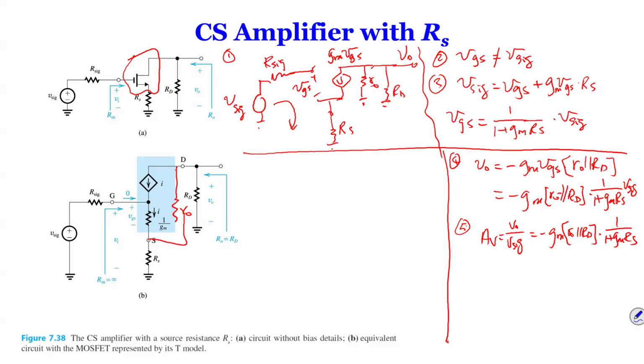And my RO will be connected between D and S, okay? So if I do that, instead of using the pi model, you're using the T model, actually you would find this multiplicative. Why? Because the RO no longer, it's not a ground, it's actually connected with S. So this actually makes your life a little bit more complicated. And without RO, actually it's simpler.